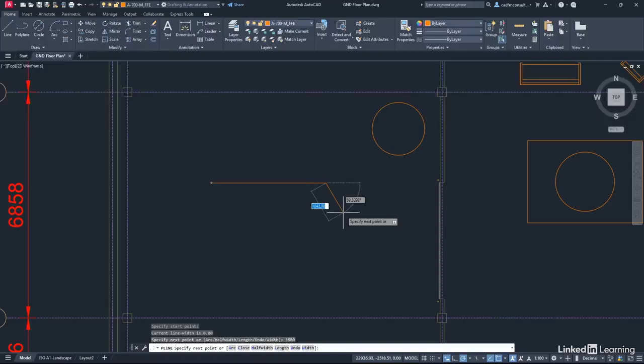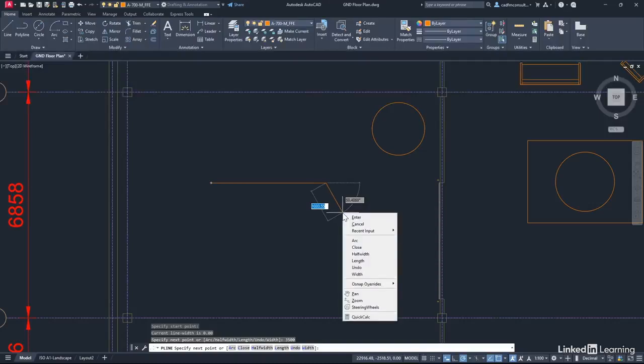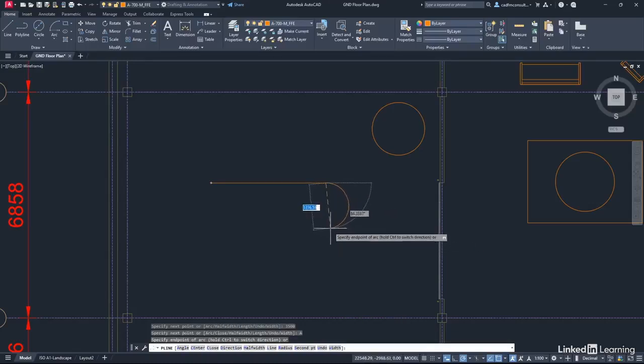Right click on the mouse. Because it's context sensitive, you're now working with functionality in the polyline command, and you're going to select arc. Now, you'll notice if you drag vertically downwards, the polar tracking kicks in. I can then use direct distance entry and type in 2500 in the box. Press enter to confirm, and that places an arc that is basically diameter of 2500.